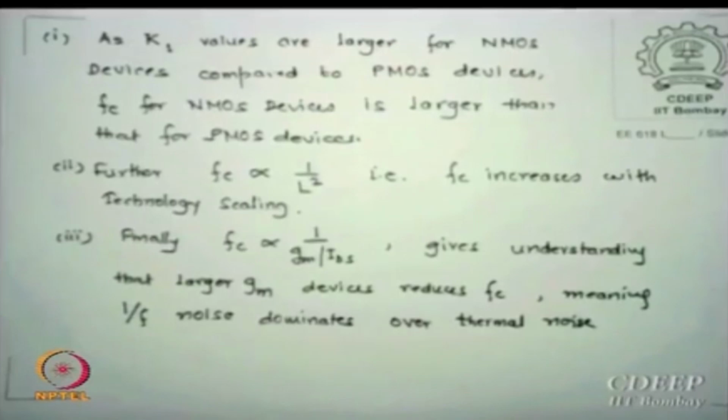What is the larger GM problem? Let's say I hold GM larger, then proportionally I will increase IDS because I maintain GM by IDS. Larger IDS means what? Power dissipation. So the first hit I got is that I reduced noise, but I hit my power dissipation, which was decided earlier only by slew rate, the net current available to you at the ISS for the differential amplifier, and it is also decided to some extent by the heat sinking possibility in the device.